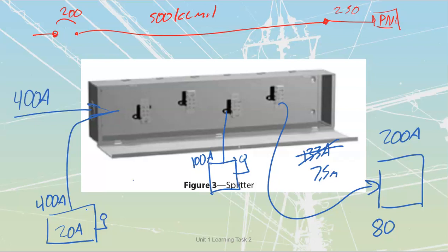So if you know what your loads are, what you've got to feed out of these splitters, start with your small loads. Make sure that you block out. Don't mount them right away, but just measure up and say, yeah, I'm going to put that in place. I've got a couple of 30 amp disconnects for some AC stuff. Then I've got 100 amp disconnects, 200 amp disconnects, etc. I would always start with my small ones, tight in, because then I can go small wires to small disconnects for small loads. The next size up, if I've got to go to a 200 amp panel for an 80 amp load, is not as much of a shock as if I've got to go to a 400 amp off of a 20.